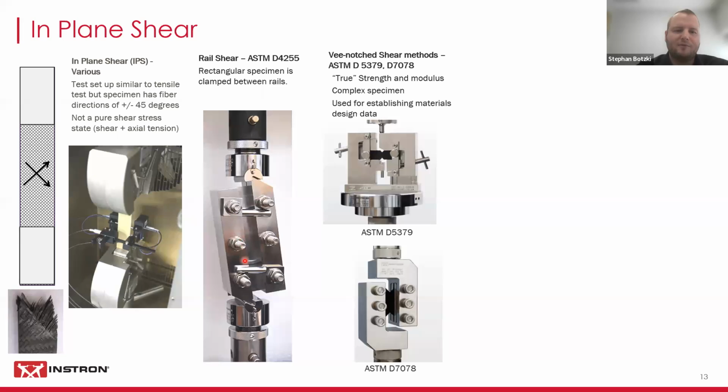So you're going to have here the bolts that you actually use to connect your rectangular specimen to your fixture. But drilling holes in composites is not made very easy, and it's also a risk of damaging the specimen. So a lot more specimen preparation compared to the simple coupon that we're using here.